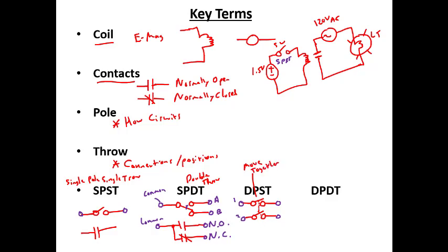And so this would be the type of switch that you would use for a 240 volt circuit, and you'd have two separate contacts, so you could connect two hot wires to this. This one, if we were looking at the contacts on a relay, this would look like this. We would use this. This would be a 2-pole contactor.